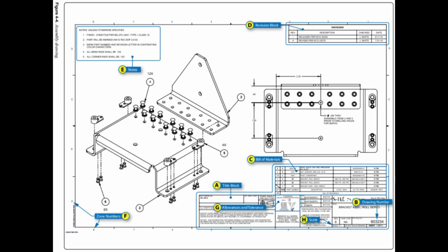Notes. Notes are added to drawings for various reasons. Some of these notes refer to methods of attachment or construction. Others give alternatives, so that the drawing can be used for different styles of the same object. Still others list modifications that are available. Notes may be found alongside the item that they refer to. If the notes are lengthy, they may be placed elsewhere on the drawing and identified by letters or numbers.